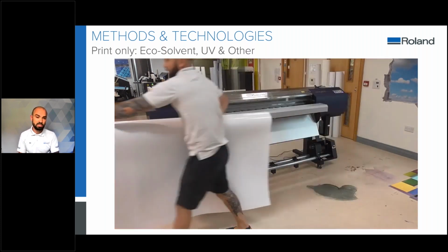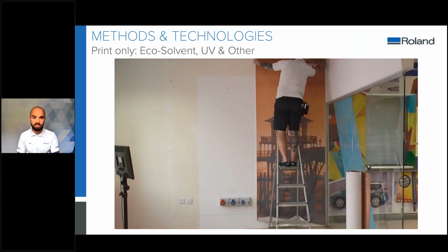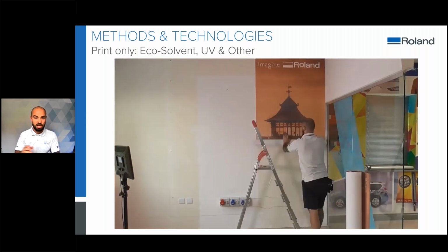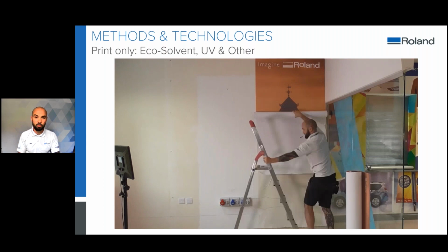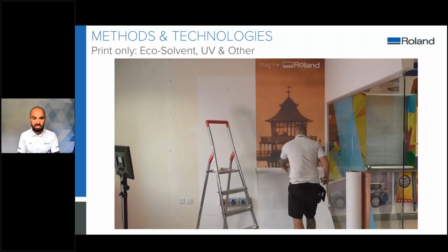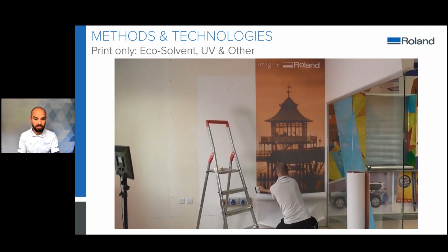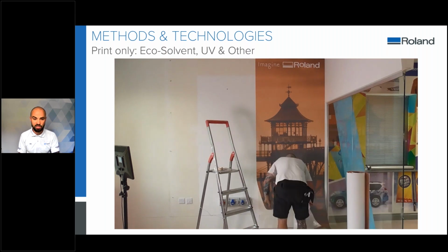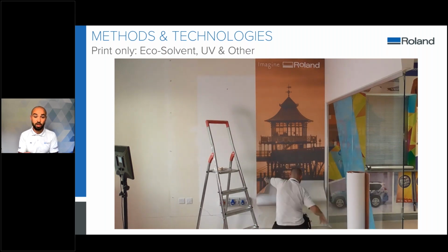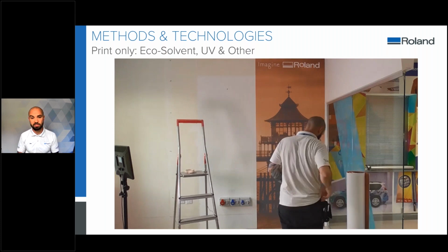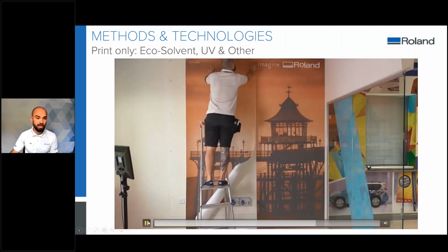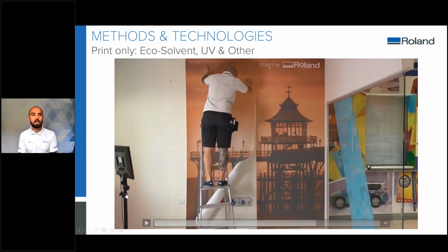So after they were printed, we just went and cut these down into the 2 tiles and started by, again, applying from the top in this example. So again, a really easy to apply material, just pulling off the backing sheet as we work our way down the material. In this example, we had 1 overlap, which was 20mm. So the overlap amount that you have, just going to pause there for a second, will depend on either the fitter or the type of material that you're using. So as a preference, whilst I was applying this one, I just wanted a 20mm overlap.